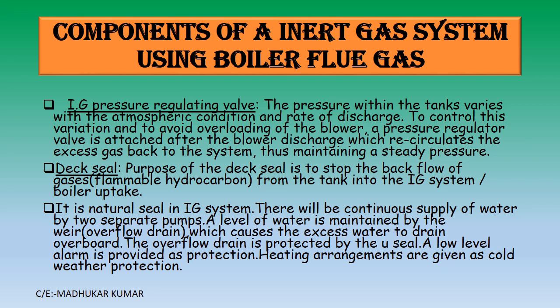Deck seal. The purpose of the deck seal is to stop the backflow of gases from the tank into the IG system at the boiler uptake. It is a natural seal in the IG system. There will be a continuous supply of water by two separate pumps. In a deck seal, a level of water is maintained by the weir, that is the overflow drain, which causes the excess water to drain overboard.